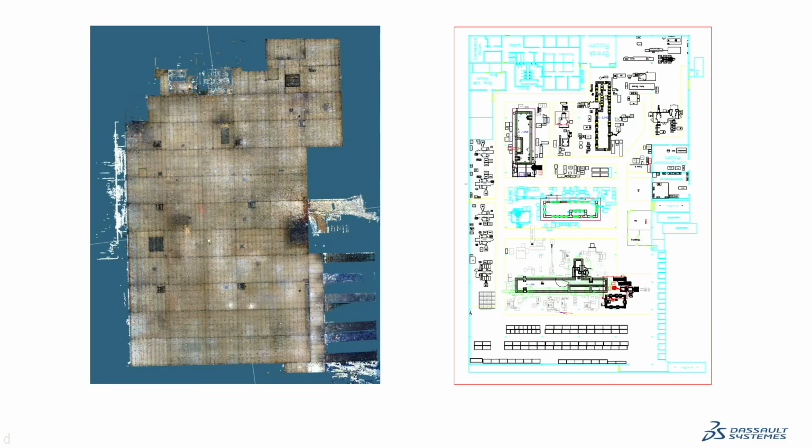That's why I was working with a customer a couple weeks ago. He did a bunch of conveyors, and they had some new ones that they designed. So we were going back in there and setting up the parameters, because then when he brings one in, he puts the parameters in there, and then he can update it. The one he did was a belt conveyor, so he was changing the belt length, the width, the height of the frame, the legs, and so on. You can do that, and it makes it interactive right away. That way he just brings one in, and then he can change all those parameters.